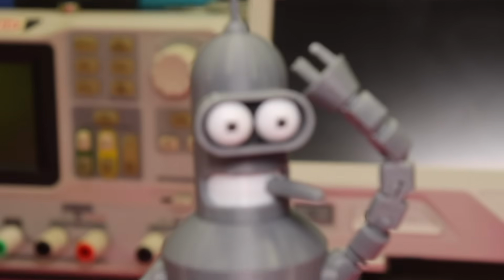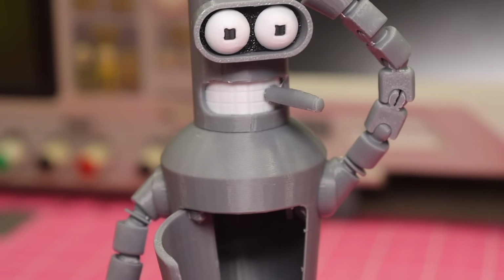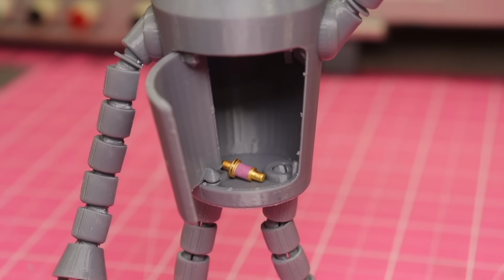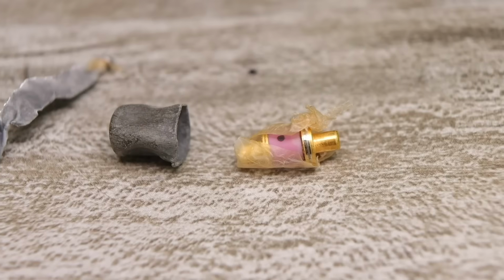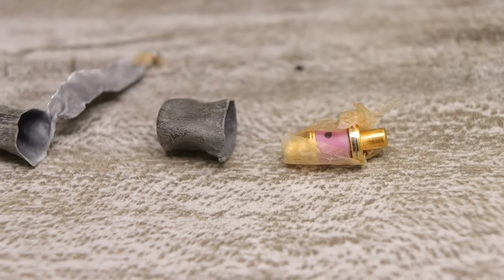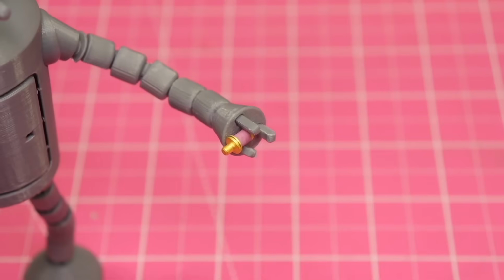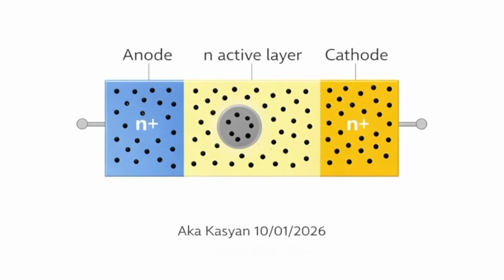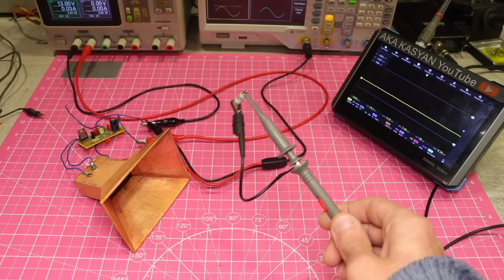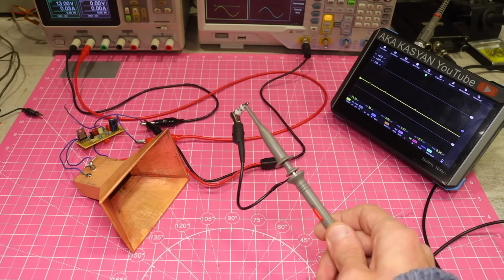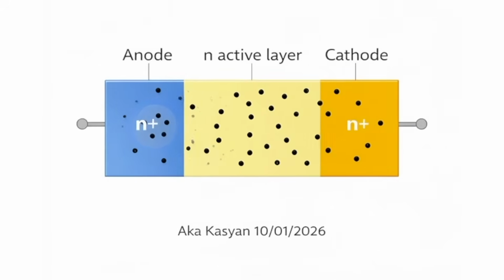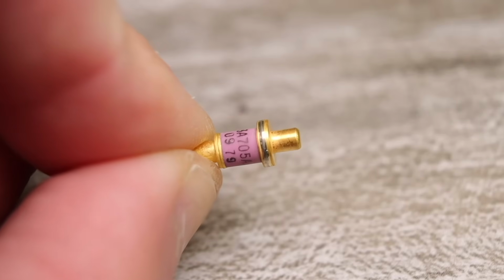Is the Gunn diode used in the modern world? Yes. And it's not about nostalgia for old military technology, but a consequence of fundamental physics. The Gunn diode is not an amplifying element like a transistor, but a bulk self-oscillator operating on the electron transfer effect. Oscillations in it do not arise due to external feedback in the circuit, but due to the moving electric field domain inside the crystal. This fundamentally distinguishes it from a transistor.